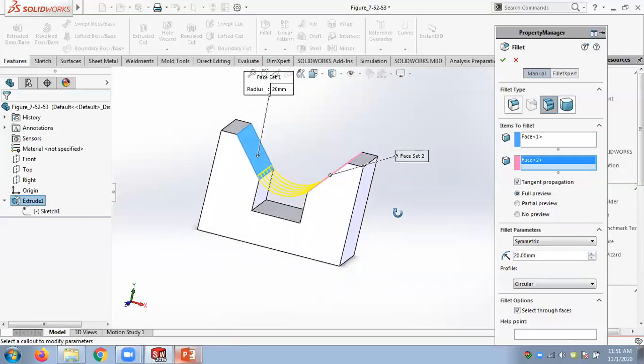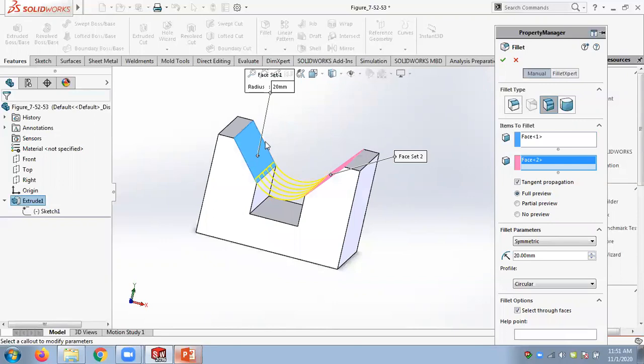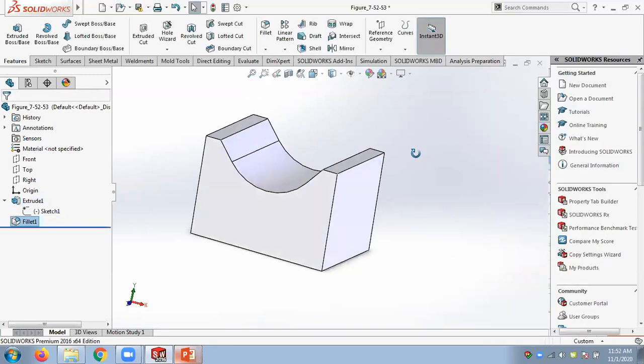So the 20 millimeter, the idea here is if I put a 20 millimeter cylinder here, it will fit to this location. But if I try to put it 19 millimeters, it's okay still. If I put an 18 millimeter cylinder here, it will fall here. So you can't get a fillet. So the minimum value is 20 or 19. If I have 30, the fillet will be this way. So if I increase the amount, it will go out of the boundaries. So this can vary.